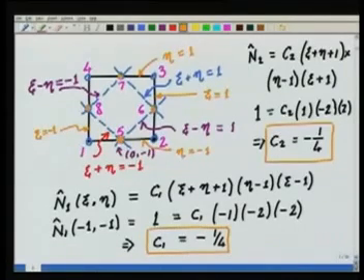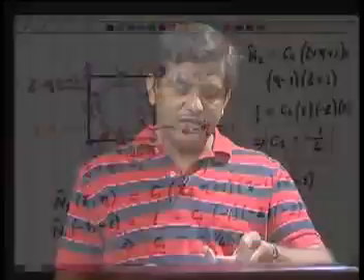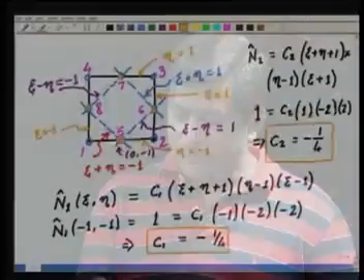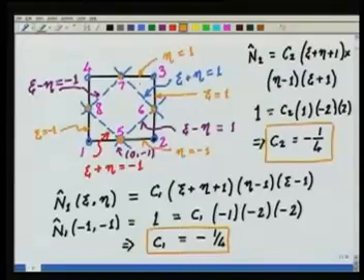If we are talking of quadratic on the edge, on the top edge, shape function 4 should look like the one-dimensional first shape function, shape function 7 should look like the second one, and shape function 3 should look like the third one-dimensional shape function. So N7 on this edge will look like this, and then it comes down to 0 at all other points.